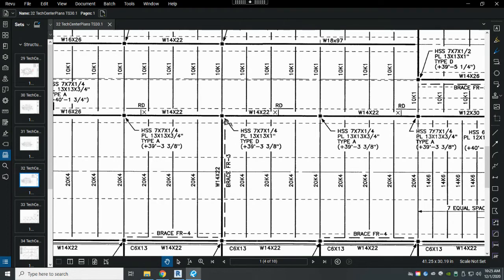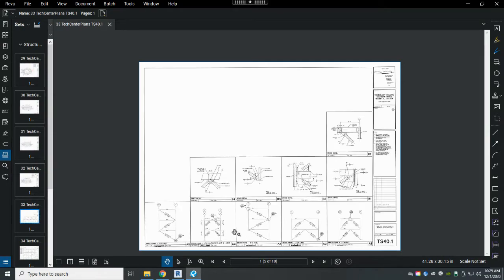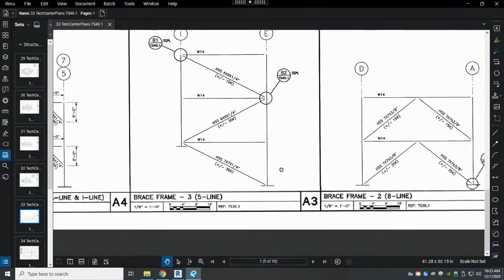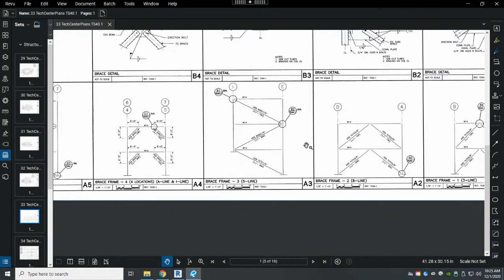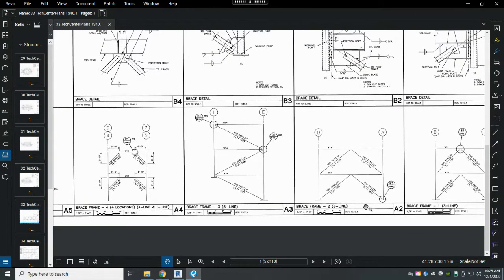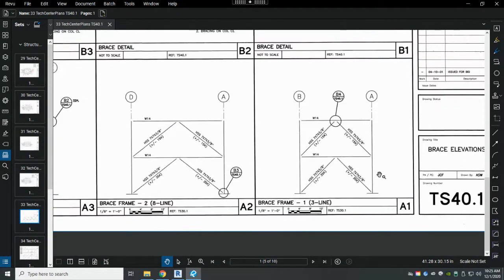So if I were to do an elevation of that, looking at it in this direction from the same direction as the detail, that's what that detail is explaining right there. That's what we would see, is that cross bracing moving up and diagonally supporting those columns and the floor framing to prevent them from buckling. So that's how you read the bracing details.